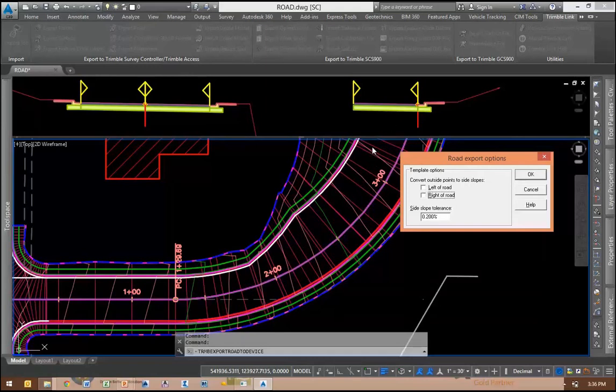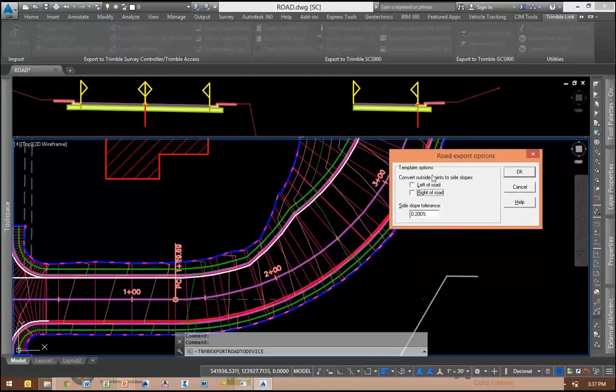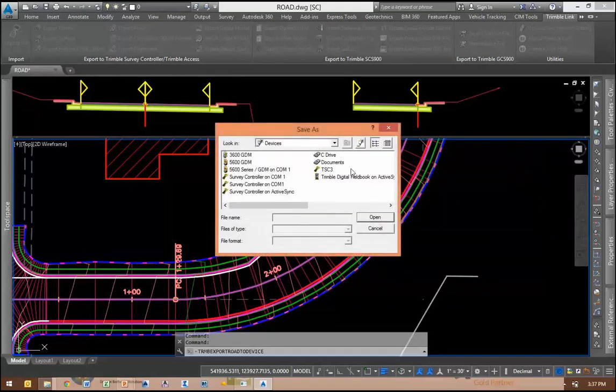Where it can be advantageous is if you don't have any targets except for surface targets. Because what it'll do is put you in like a slope staking routine, where it'll take the slopes as defined in here, 2-to-1s, 10%, whatever it might be, and it'll calculate the actual catch point in the field, not the grading limits as I've virtually designed in here. Okay? So you want to hang on to your targets, leave this checked off. Basically leave it checked off all the time.